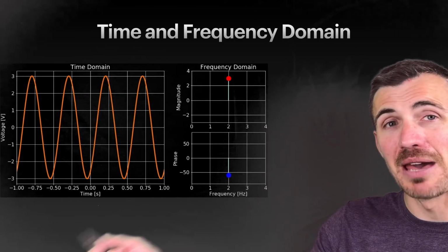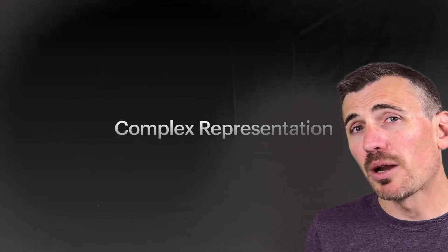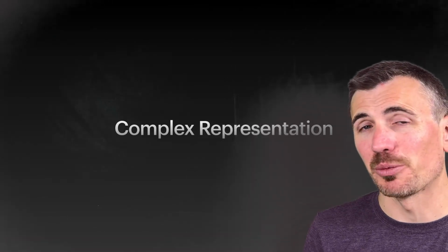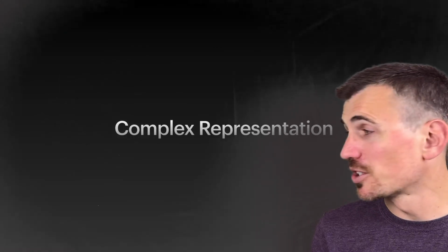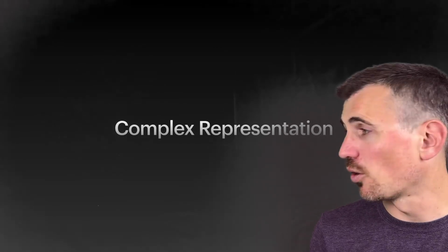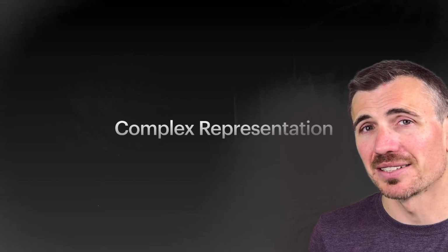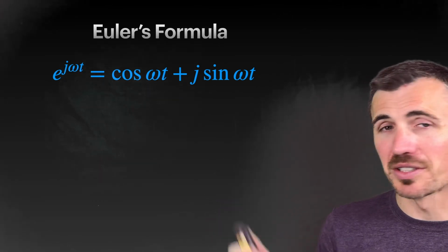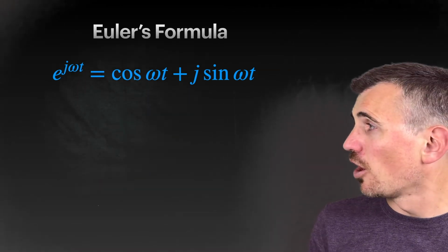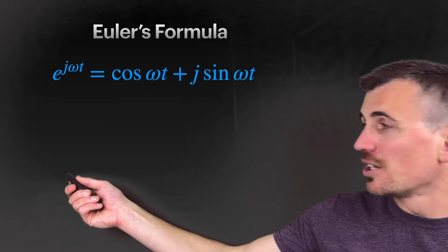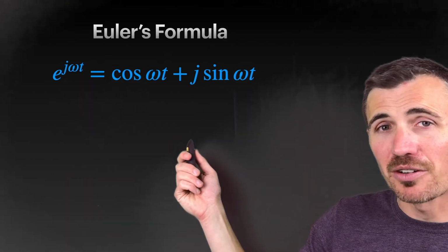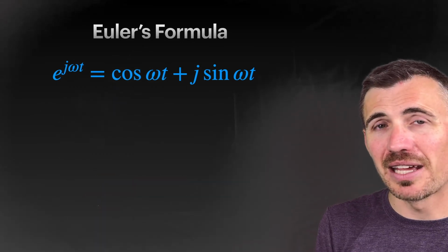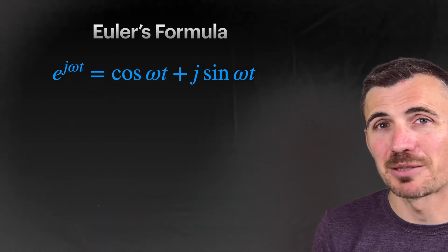A complex number has a magnitude and a phase. So we're going to represent our voltages and our currents and our resistances, or impedances as they will be called, by complex numbers. And what's great about this is these complex numbers already have built into them the magnitudes and phases. But it gets even better, because there's a beautiful theorem in complex analysis, Euler's theorem, that tells us that a complex exponential automatically relates trigonometric functions to complex numbers. Not only that, any complex number can be written as a magnitude times this complex exponential.